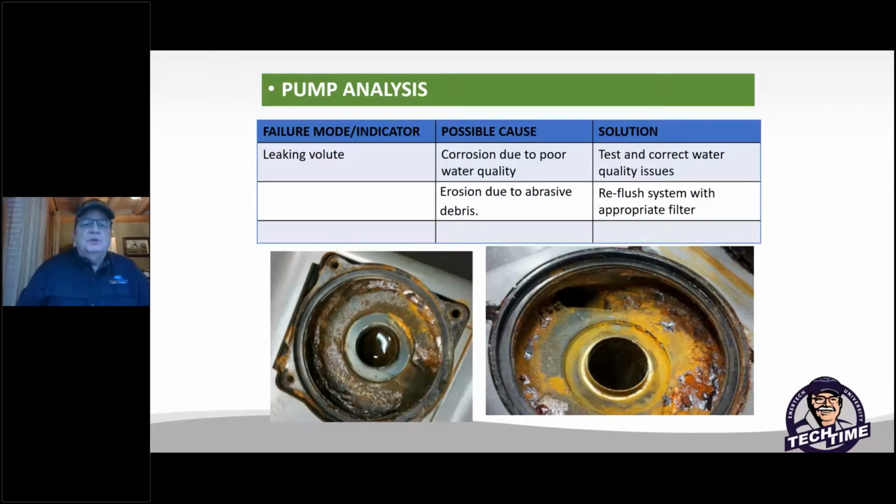There's another picture showing you some corrosion, poor water quality. You get poor water quality, things plug up and block up. You may get some turbulent flow inside and eat away the volutes, and now the pump is gone, the volute is gone, now you got another service call. And if it's under warranty, guess what? None of us win. So bear in mind, protection is very, very relevant and should be something added to every one of your systems.